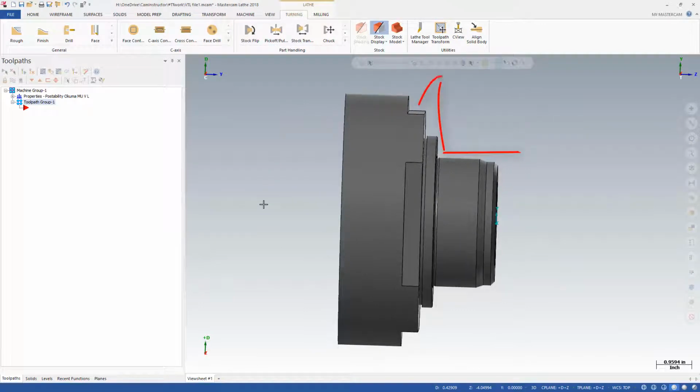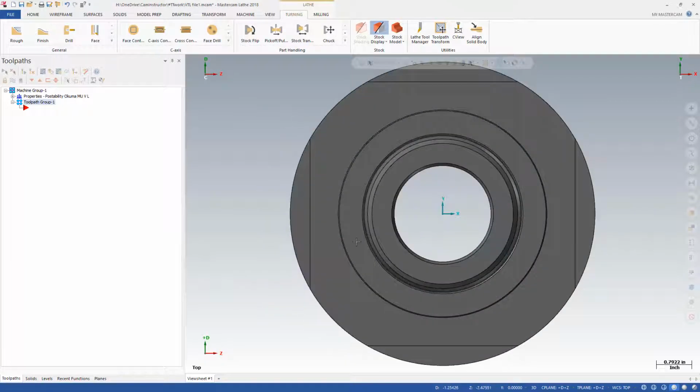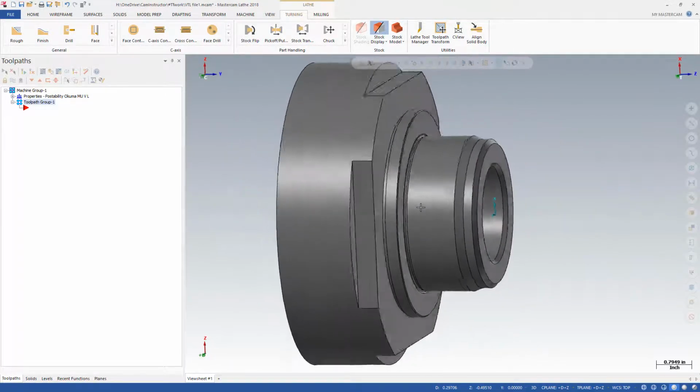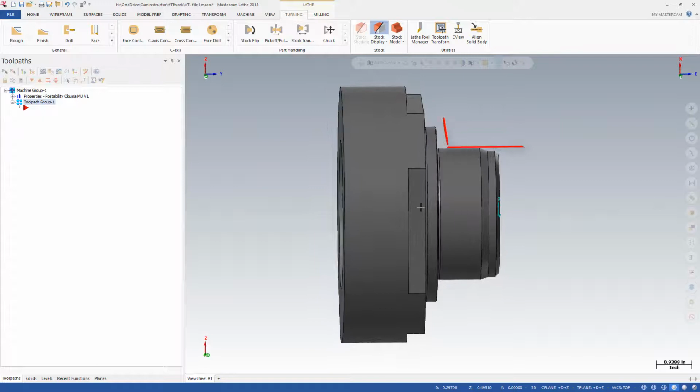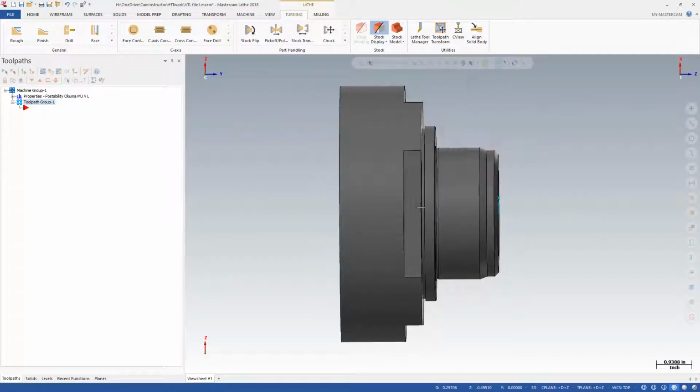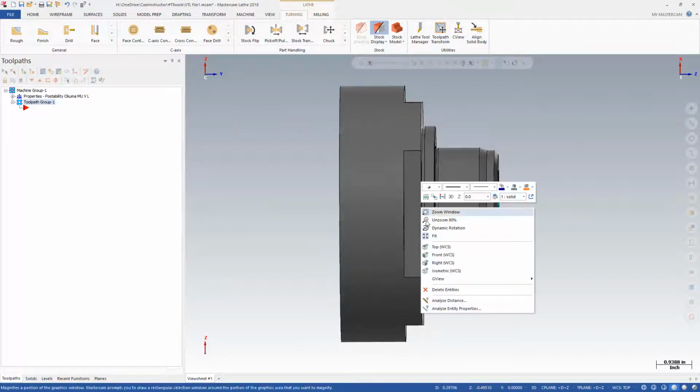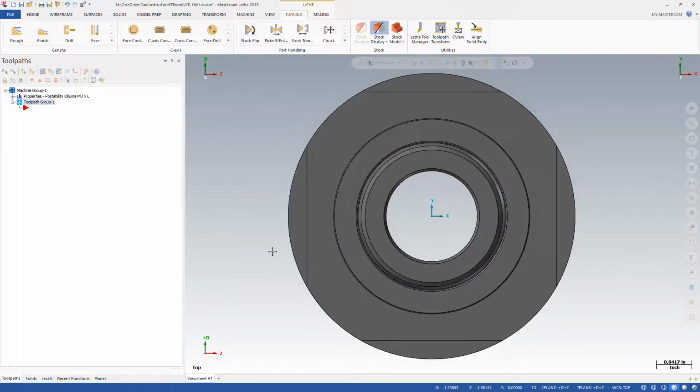This results in what could be interpreted as the tool cutting along the back side of the part. If this machine tilted with a B-axis rotation, the new plane would be created relative to the back plane and results in what could be called cutting along the right side of the part. Basically, you're going to define a plane so the tool is cutting perpendicular to the tilting axis.